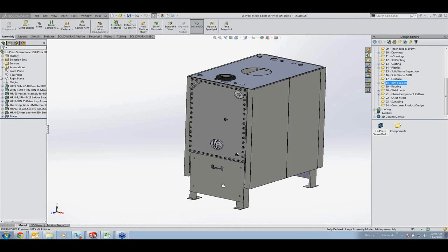A very powerful tool that's new in 2015 is the flatten surface. Simply select the surfaces, the faces on the surface, excuse me. I think I missed this one here. There we go. And select a point to stay stationary. Okay, that didn't work because this face was missing. So go ahead and select that face again, and then select the vertex of that face. I can also choose control curves to control the shape of my flattened surface.